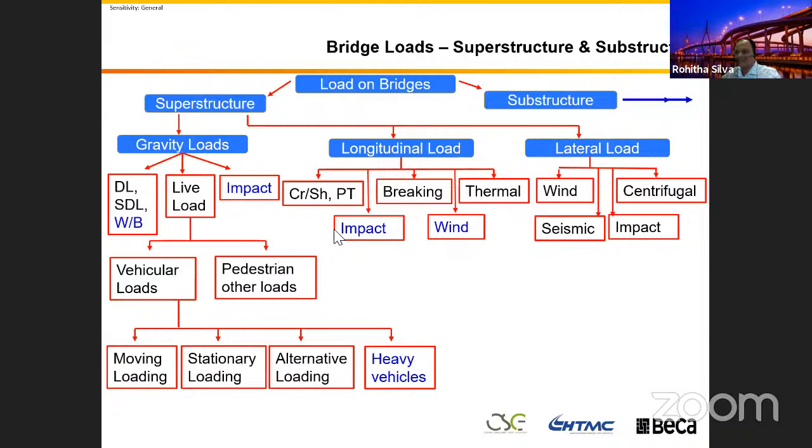In addition to that, the effect due to impact creates a load on the structure. When there is an impact on a barrier, we don't know the impact angle. Because of that angle, one of the components of the impact will be translated into a longitudinal load.